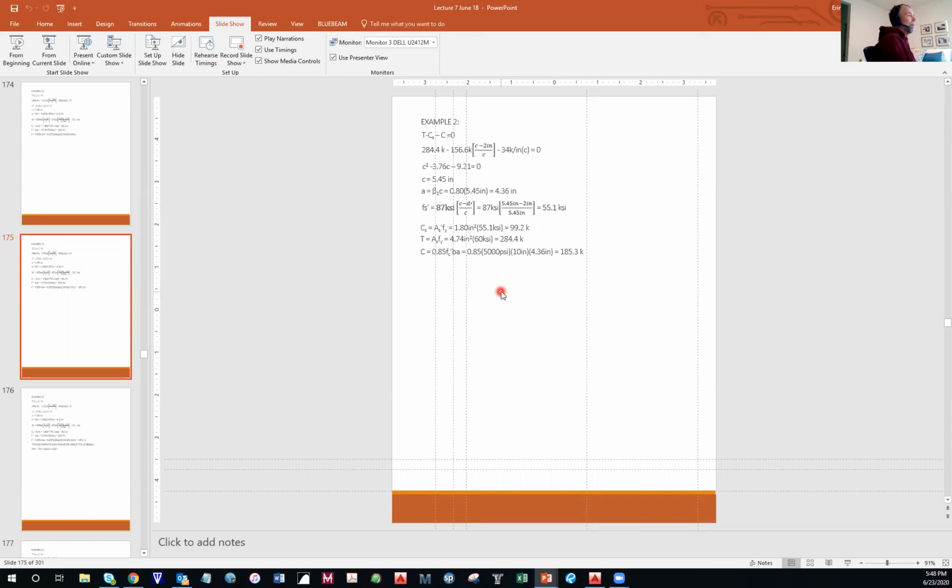But if you find that you can't possibly get enough flexural steel, tension steel, without being over reinforced, then you have to add compression steel. And to solve those, you do those like example 3 that we just did, where you break the beam up into 2 pieces and you solve for the one and then you solve for the other and you add it all back together. Does that kind of help the flow of how to do these compression steel?